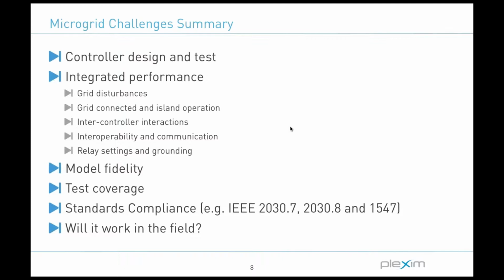But to really validate the system performance, controller hardware in the loop becomes a powerful tool to ensure that your testing is accurately capturing the real controller behavior. So when you actually deploy the project, you can use exported parameter sets from the software and benchmarked firmware versions, and compare that to what's in the field, versus there being some obscure scaling factor hidden deep in your model or code.